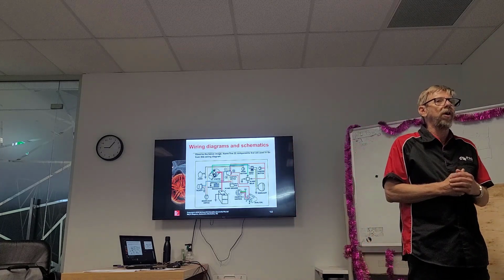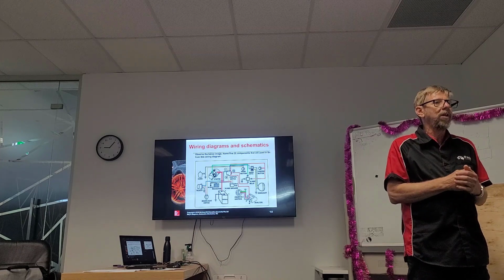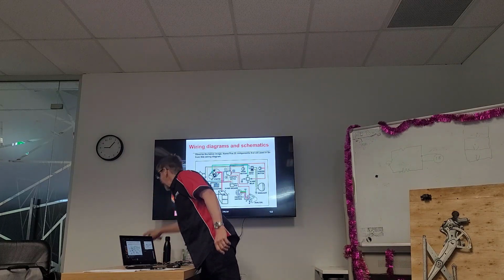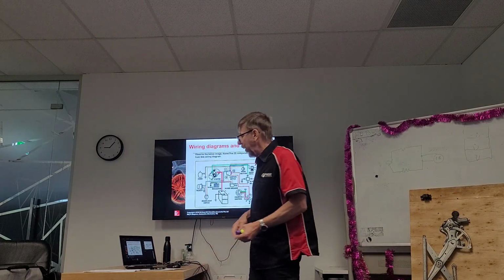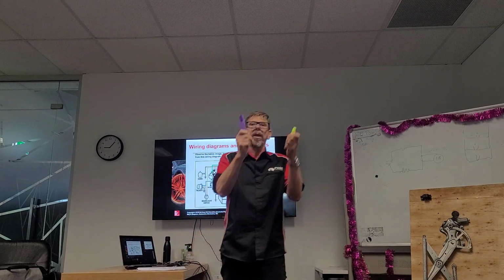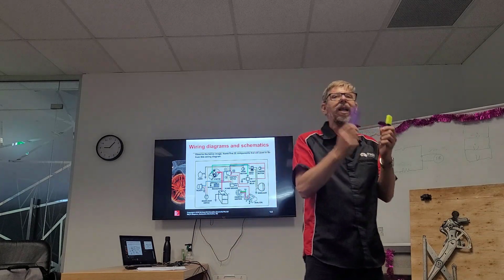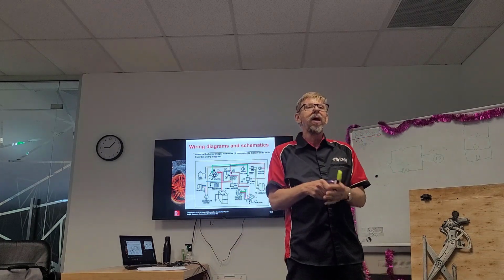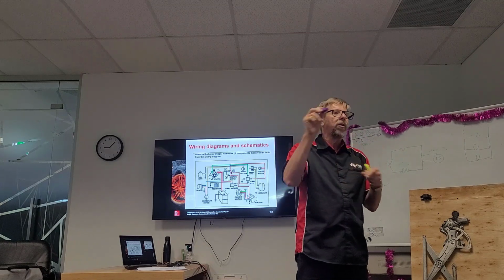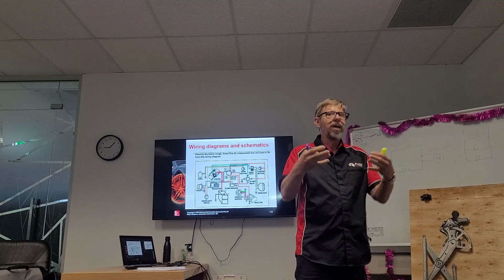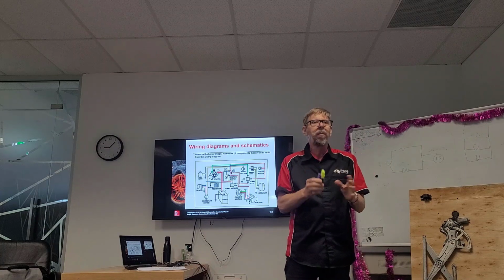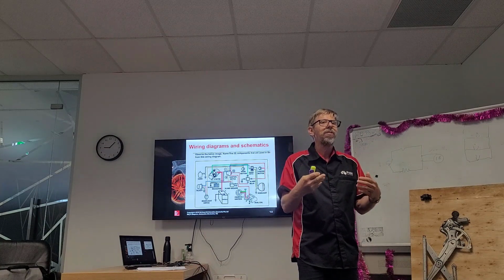And that's how we look at wiring diagrams. We go and look at what's joining the wiring diagram. Even though this one is in colour, most wiring diagrams are in black and white, so I would use some colours, not necessarily these particular ones. I normally use a red for the power. I normally use a green for the grounds. I work it out that way. And when you highlight the wiring diagram, whatever you're looking at stands out and becomes much more clear. So it's not that complicated, and that's where we're going with this today.